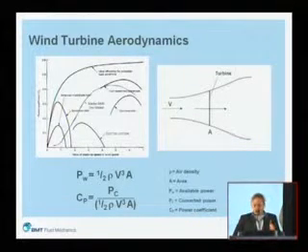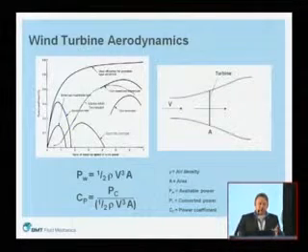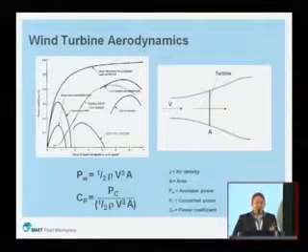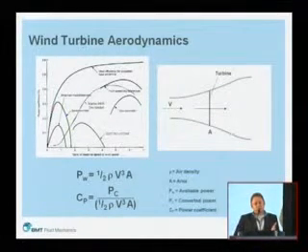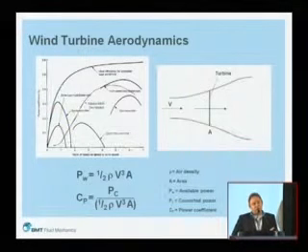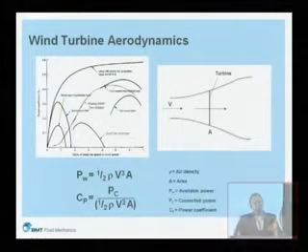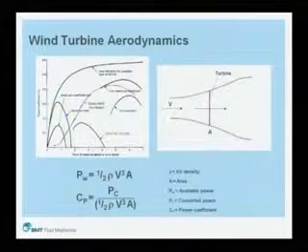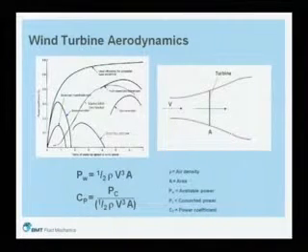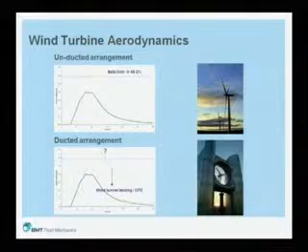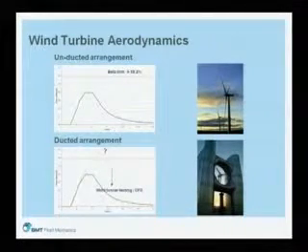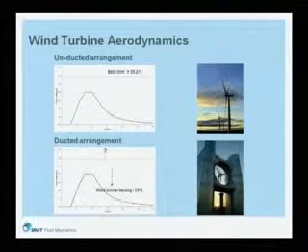In the context of building integrated turbines, the fact that the power is proportional to wind speed cubed is interesting because you realize that wind speed increases with height. If you can put a turbine high up in the wind, you double the available wind speed, you multiply the available power by a factor of 8. So I guess that's one of the attractions in theory of putting large-scale turbines on buildings, because you can use a building to get the wind turbine high up in the air.